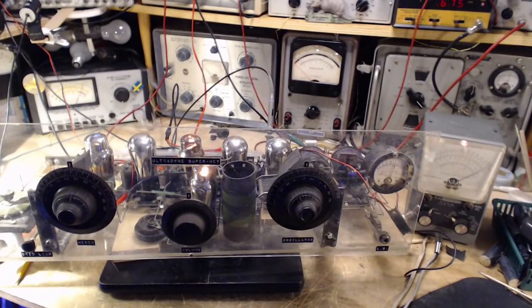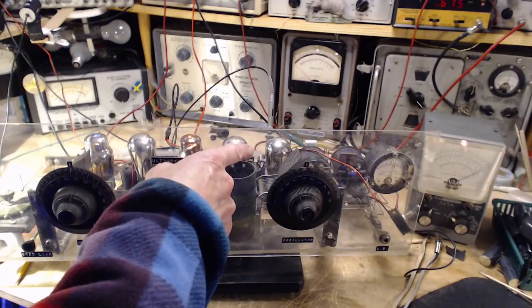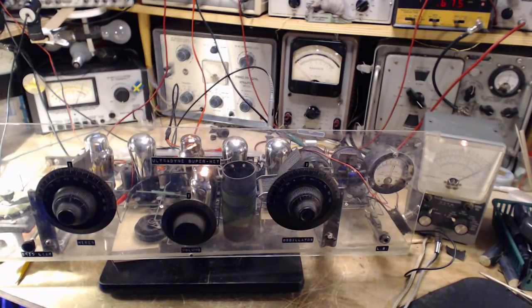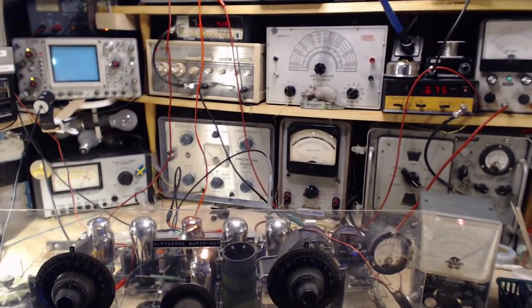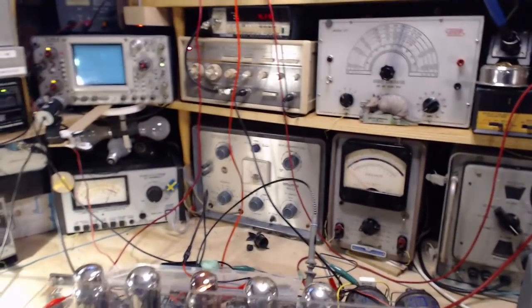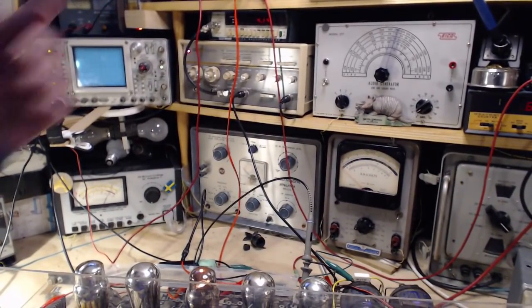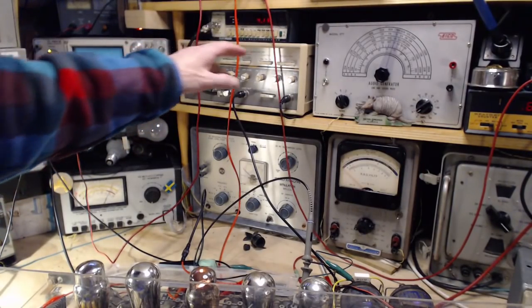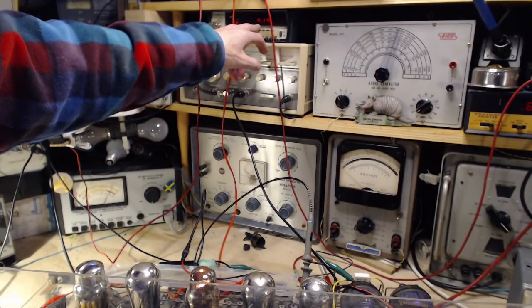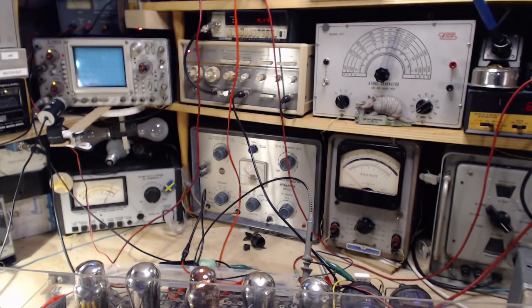Okay, so I've been just fiddling around here. That tone you're hearing is coming out of my signal tracer. My signal tracer is listening to the output stage of this radio, and that's what it's hearing. And I got there for reasons I don't understand, so I turned the camera on to see if we can sort this out. What I did was I stopped the sweep generator from sweeping. It's at a fixed frequency now. The frequency is 4 kilohertz. That sounds like 4 kilohertz, come to think of it, doesn't it?